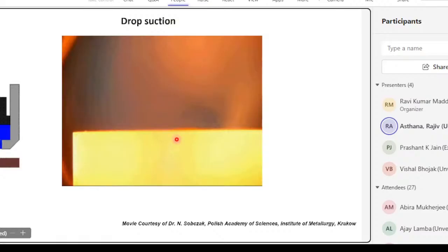Another interesting thing we see is that under vacuum, metal droplets actually begin to dance because there is some gas evolution from the solid, or degassing, that causes the liquid to bubble up or jump on the surface here. You can see right now the droplet has melted and is stationary, and then it will begin to hop because of the gas evolution from the surface.